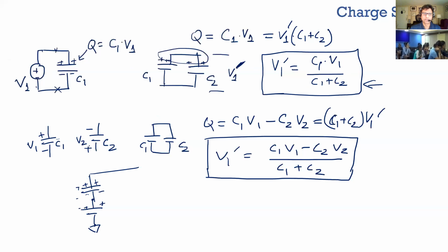So if I take this capacitor and just put it in series, then with V1 and V2, say V2 is negative, it'll just be V1 minus V2, because there's no way for the charge to get shared now. This Q2 charge has nowhere to go. For it to move to something else, that charge should have a path to ground or VDD, some low impedance path. If I just do this, that charge will remain as it is. So remember that as well.